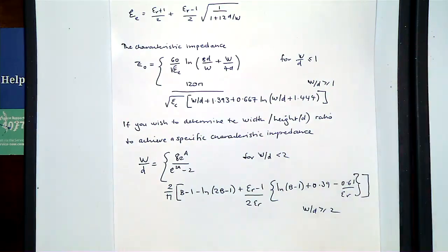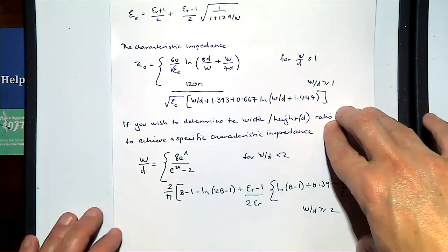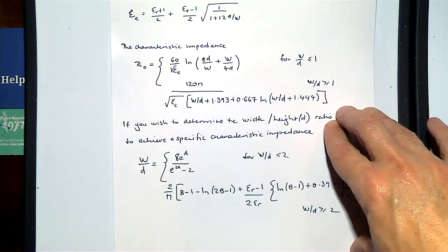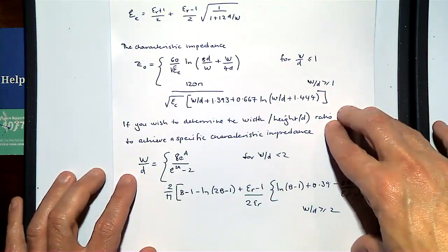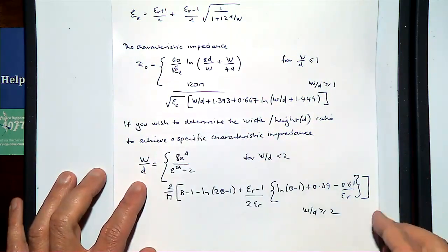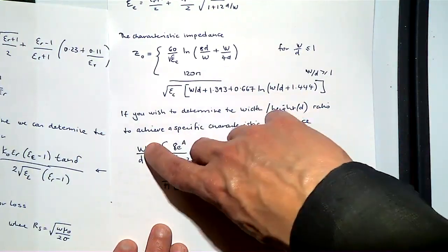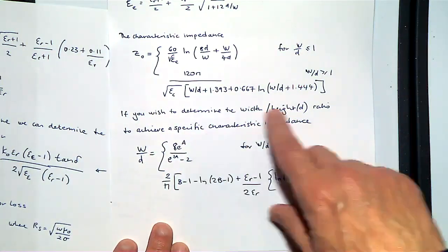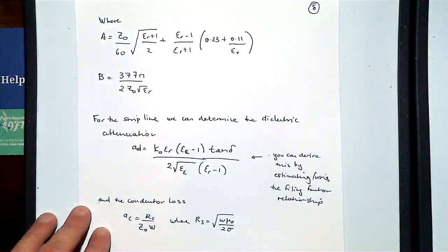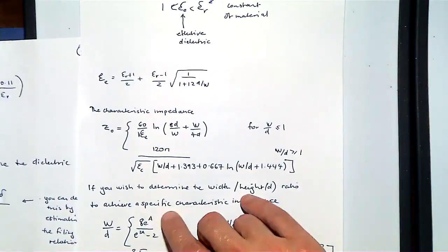Anyway, so there we said, suppose we wish to determine a microstrip with a particular characteristic impedance. What we do is we use the formulae in order to work out the width to the thickness of the material, where essentially we are given these other two values. We got the width to the thickness of the dielectric material written in terms of these two formulae, where A and B are essentially the two values that are defined in these two equations.